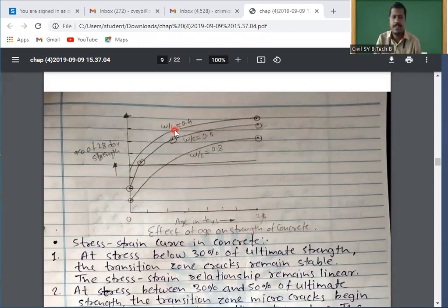No, if temperature is more, we are having some water absorbing agents, some super plasticizers or plasticizers which will help us to maintain the workability of the concrete without compromising on water cement ratio, by reducing the water cement ratio also, or by keeping it the same. Okay. So please remember a very simple part. Take the water cement ratio as you have designed it or as you have calculated or as it is recommended. Okay. Don't go for more water cement ratio.